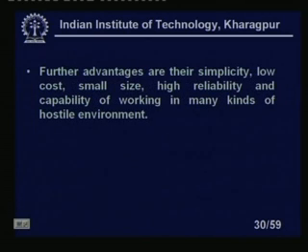Further advantages are the simplicity, low cost, smaller size, high reliability and capability of working in many kinds of hostile environments. Hostile environments, where there is dust, or a chance of a large electromagnetic field, where the electrical connection is very hazardous. You cannot use electrical... suppose I have a thermocouple and it is going through a transformer where there is a large magnetic field, it will influence the reading, because if there is a surge in the transformer, that will affect our reading. And the strip chart recorder which is recording the temperature will also have a problem. That type of problem does not come in the optical fibers. That is a great advantage of this type of device.